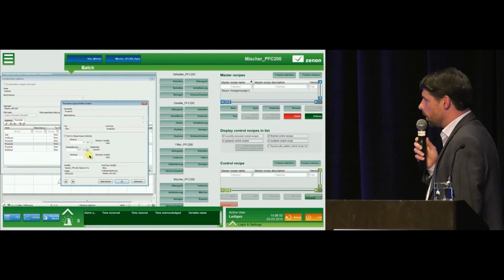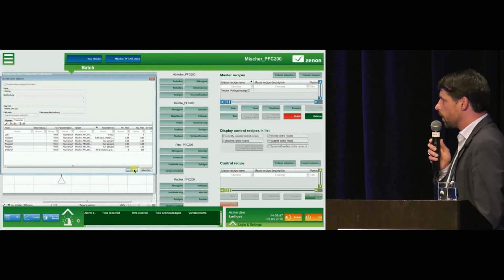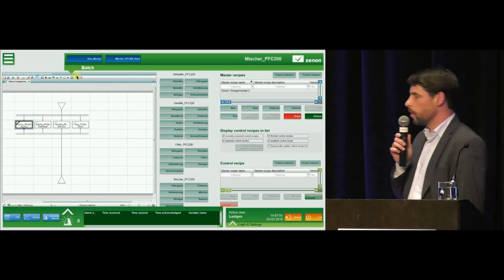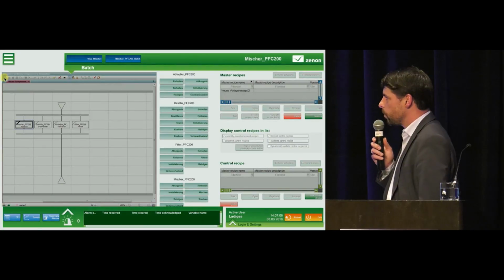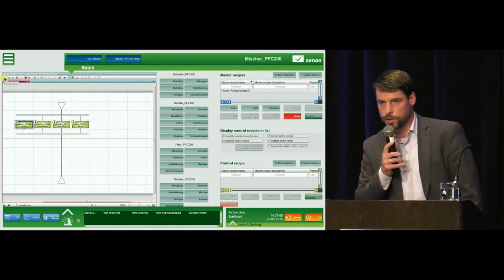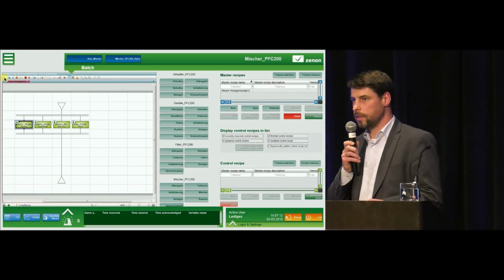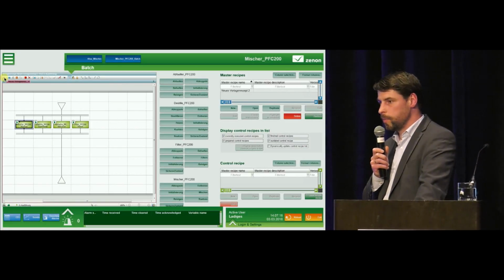And so the process plan can be started by executing the recipe. And now the production plan works. With a totally new module, the DCS system has never seen this module or this vendor before. It's only described by the MTP file.